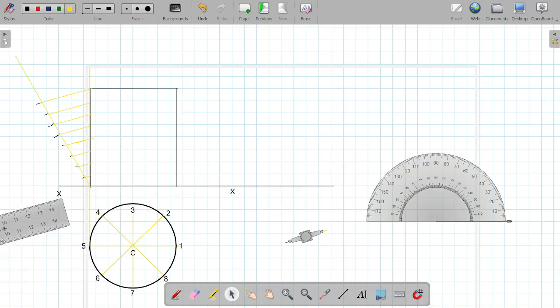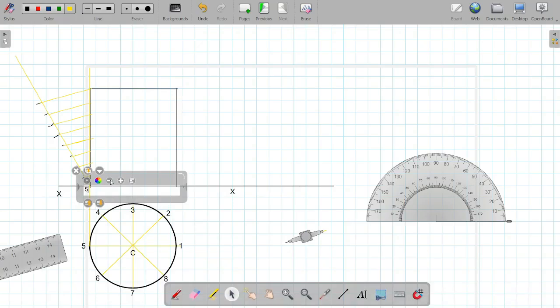After this, we will also name the points on this particular line. Now the important part is the naming part. Normally we used to give numbers starting from 1. But here we have to see the projections. If you can see that the projection from 5, we have taken the projection from number 5 till this part. So this first part will be starting from 5 only. So we'll number this point as 5. So this is point 5.